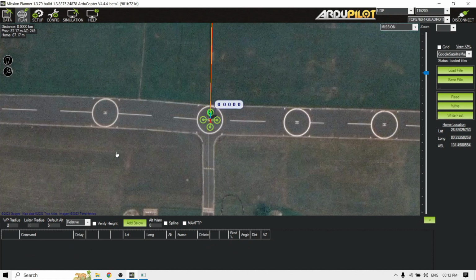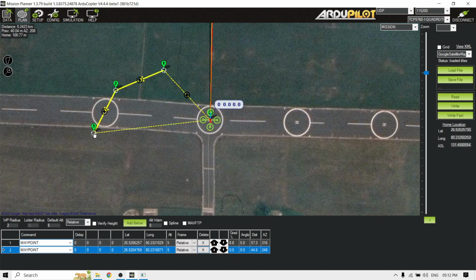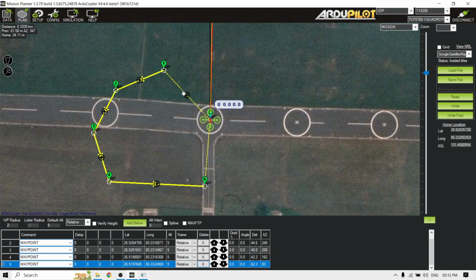Then the default altitude. Let's assume I'm clicking here, and everywhere I'm clicking, I'm selecting the positions, latitude and longitude. But what about the altitude? You can see here by default it's 5. You can double click and you can change it. There's no issue. Again, I'll make it 500, much more altitude. We can do that, no worries. But by default it would be 5 meters.